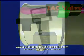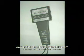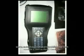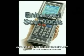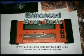The first tool employed during a minimum air rate adjustment is the IAC actuator tool. If this tool is not at hand, simply use any means necessary to completely close the IAC air passage. A scan tool may also be used in place of the IAC actuator. This is a DRB3, which is Chrysler's scan tool. In our video, we'll be using the DRB3 since we are using a Jeep in our example. However, this is a straightforward procedure and any enhanced scan tool will do just fine.